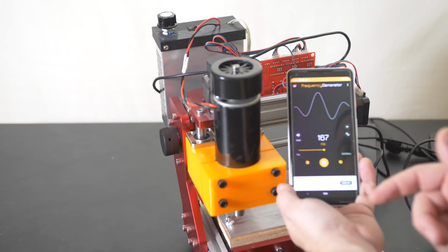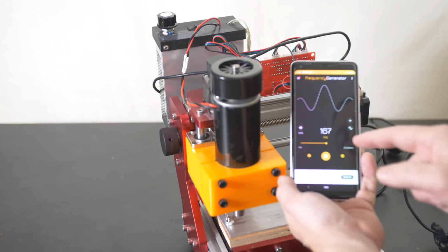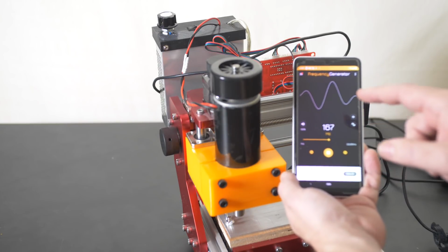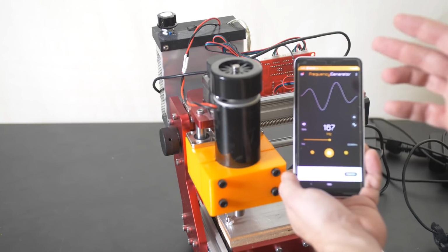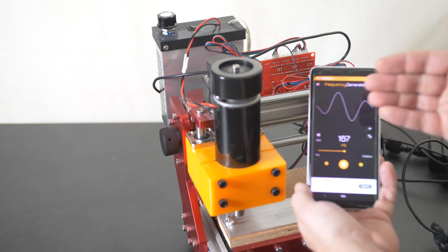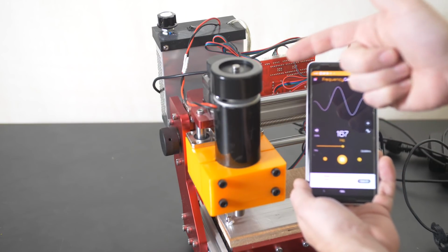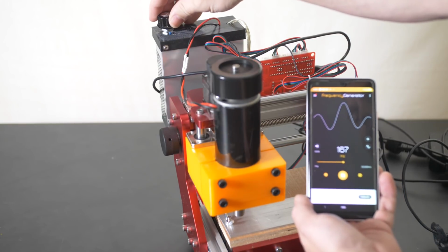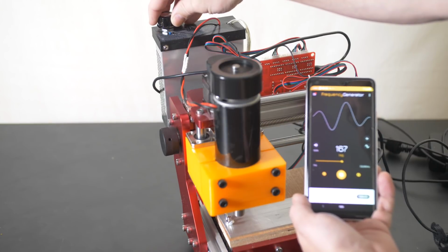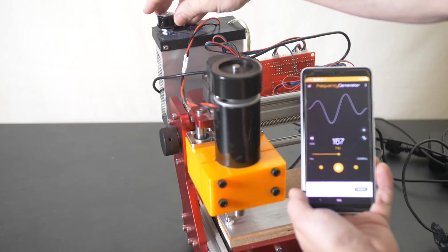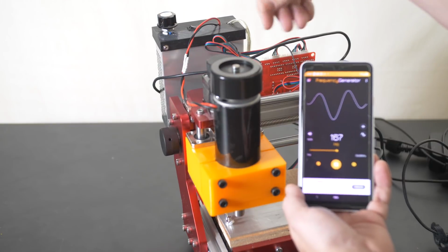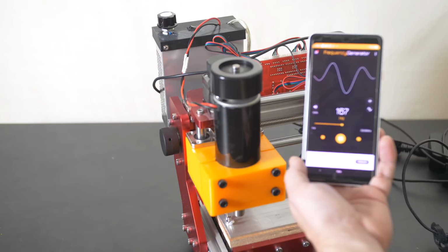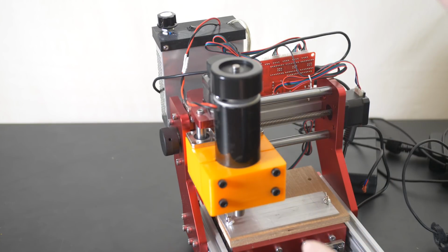167 hertz means 167 times per second. So you multiply that by 60 seconds in a minute, gives you 10,000 waveforms in a minute. So 10,000 waveforms is the noise that this motor is going to make at 10,000 RPMs because the motor's not perfectly balanced. So you can tune your motor just like you would tune a musical instrument, and in that way, without having any other special measuring device, you can figure out how fast your motor is going. Hear the motor, hear the tone, same note.